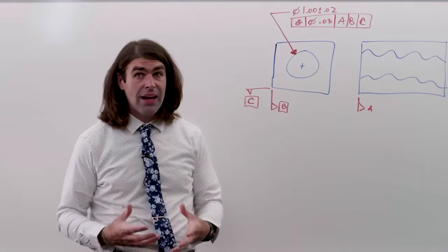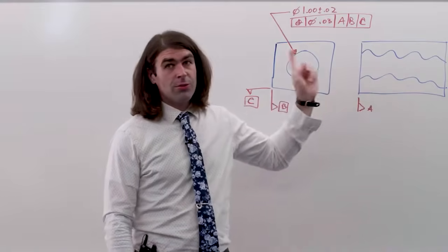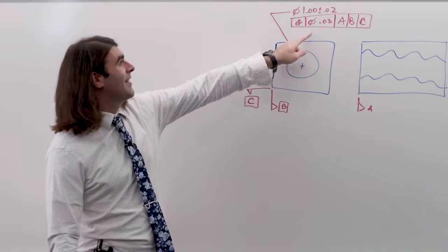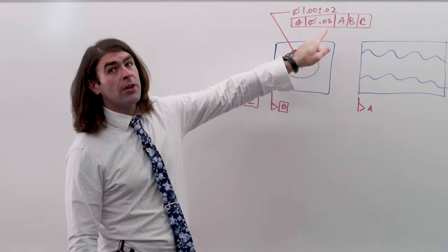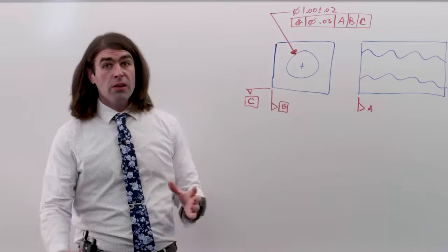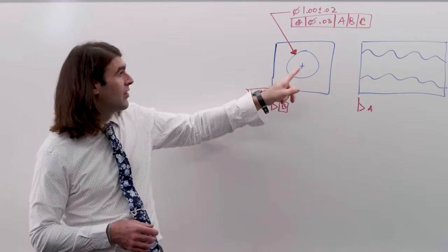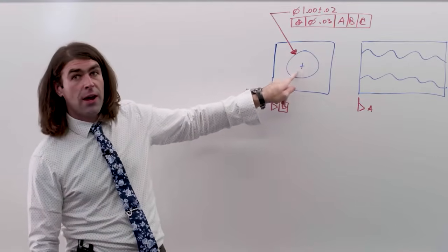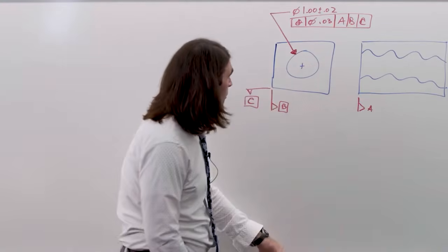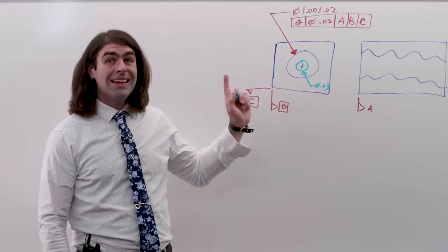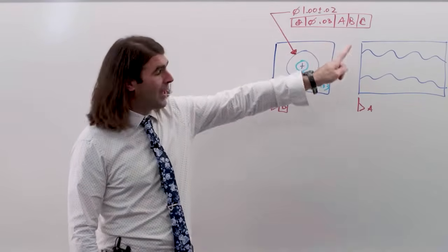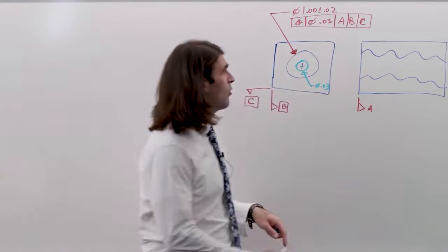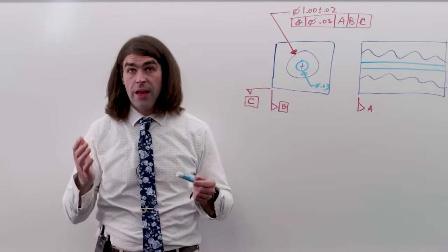So how do we decide whether this is within the tolerance zone? The tolerance zone for position is a diameter, right? We've got a diameter symbol here of 30 thousandths, located at the true position, which in this case, even without basic dimensions, we'll get to that later, is going to be on the drawing right where the center mark is. So that's our tolerance zone. Because it's related to datum A right here, that's what gives it perpendicularity. So we're going to project it over here. That's our tolerance zone for position.